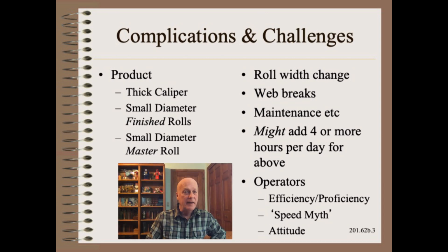With these calculations, it would be easy to see that some product situations are more challenging than others. The worst combination is small diameter rolls of thick webs, because that causes the winder to need to change out rolls more frequently. During this event, the instantaneous productivity of the ReWinder or R2R converting machine drops to 0.